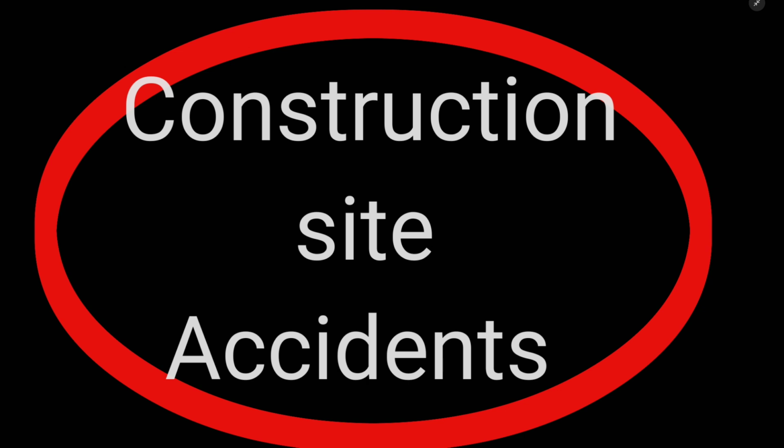Third is caught in or between object. Being caught in or between machinery is a terrifying and often fatal accident. To reduce the risk, maintain clear walkway, avoid blocking machinery, and ensure all machines are properly locked out when being serviced.